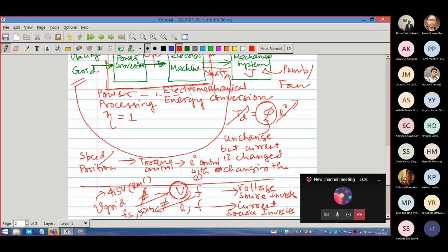Okay, we have to dynamically, as a function of time, produce such a voltage and frequency that we change torque without any variation in the machine's flux level, its saturation level, its magnetizing current level. We cannot afford to change that. So when we do that, we will be able to extract better dynamic performance on the machine. So our performance is judged by this kind of dynamic performance of the machine, not only steady state performance,